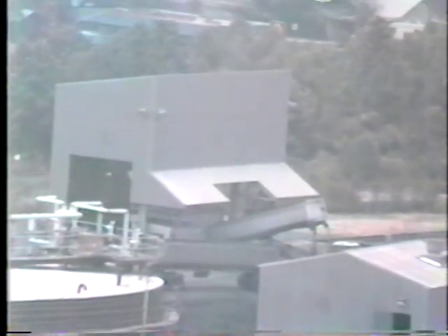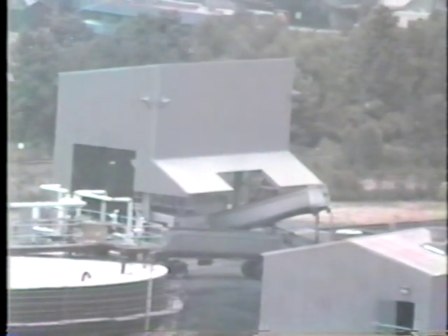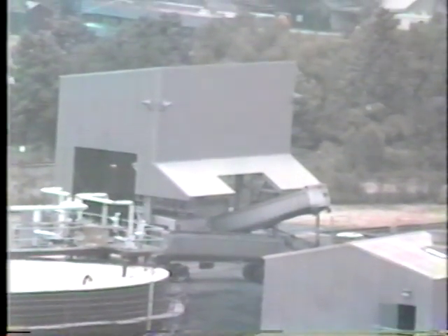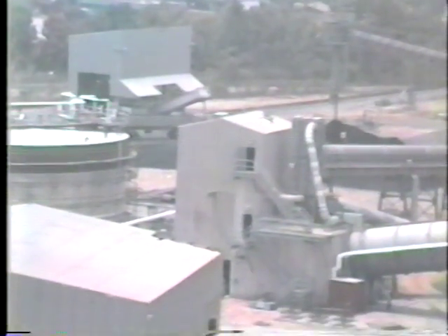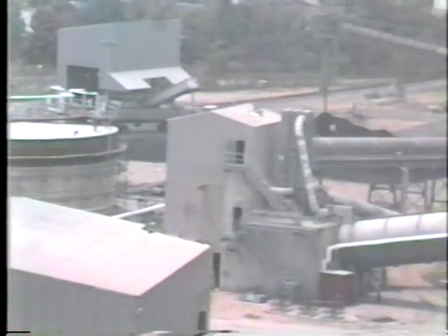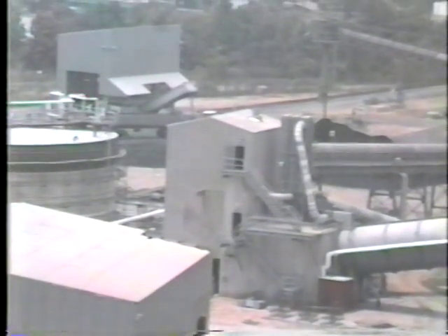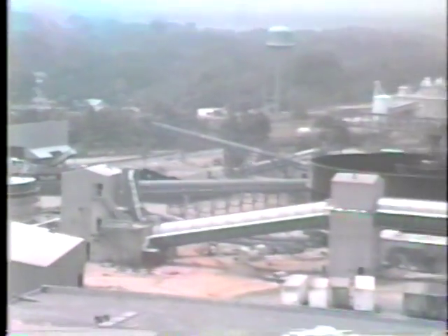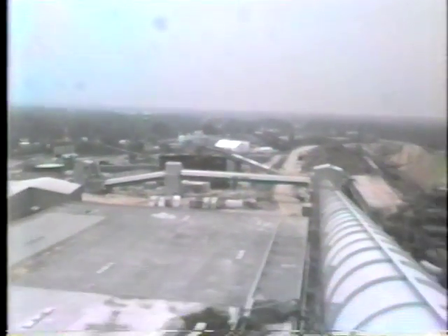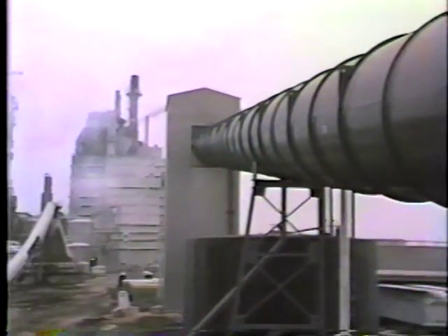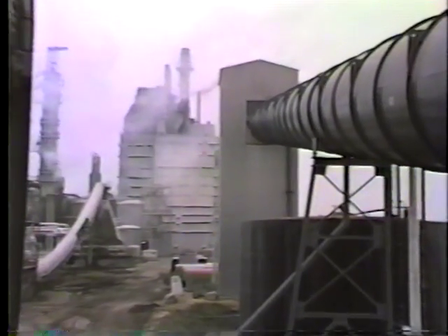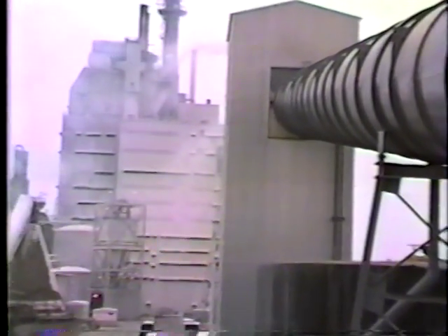Daily arrivals of coal trucks dump their loads at the scale and stockpiling area. The 2-inch by 0 coal unloads through a grizzly and is conveyorized to stockpile as shown to the upper right, or continues on up to the primary crusher house in the center building. Output from the primary continues up these conveyor galleries. There are dual conveyors that bring both coal and shredded bark and wood to the boiler. Bark is in the conveyors to the left and coal to the right.